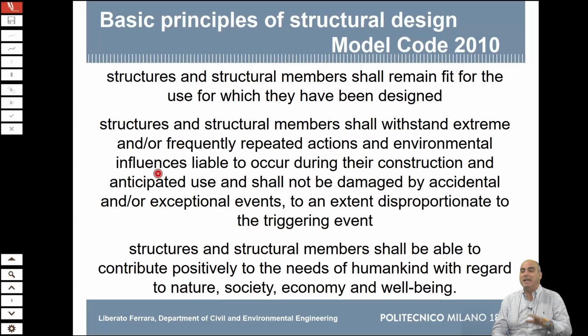So it does not mean anything that you want a certain strength grade and a certain minimum content of cement with a maximum water cement ratio, because you should specify what type of cement is there. You should specify what is the cracked condition of your structure. You should specify what is the CO2 concentration in the air, the moisture, and so on, just to make an example.